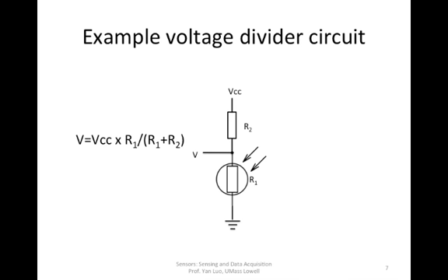So the next step is we're going to take this voltage, use it as an input to our system, and specifically we're going to use it as the input to our analog to digital converter unit, or ADC, so that we can convert this analog signal into a digital value. Because our microcontrollers and microprocessors are good at processing digital signals. We do need this digital value.